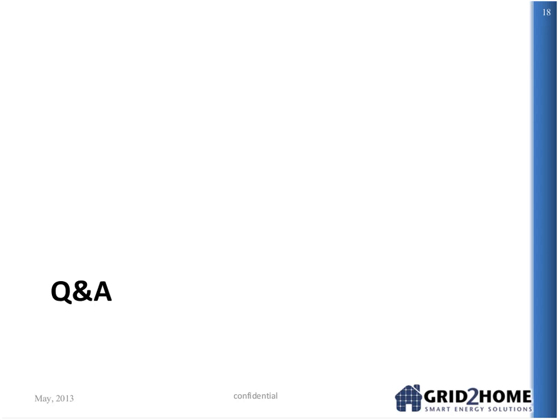No, well, William was trying to state what the U was and whether it replaces that. I believe that's being used, I think that's been defined for use on the AMI side, but it does not matter. SEP2 doesn't define what ZigBee protocol or what Wi-Fi should be. But SEP2 will run over anything that uses IP. You could run it over Bluetooth. You could run it over DECT if it supported IP. So it's got nothing really to do with the lower layers. It's really independent of the lower layers. So if someone wants to go out there and say, I want to use a different 802.15.4 PHY, there's nothing that precludes that in the SEP2 spec.